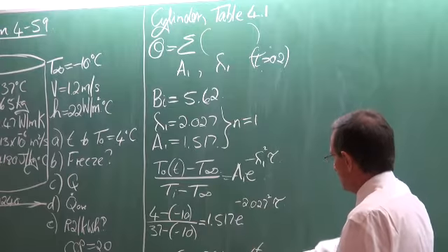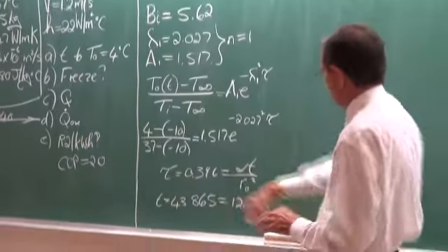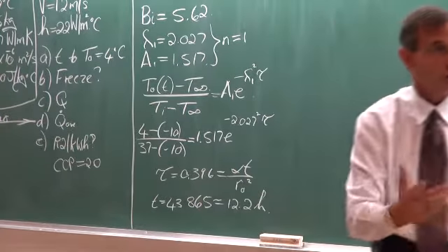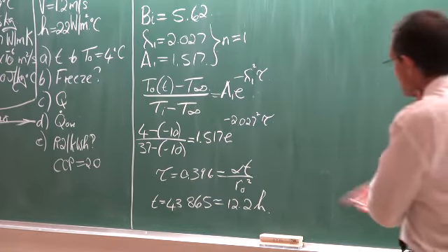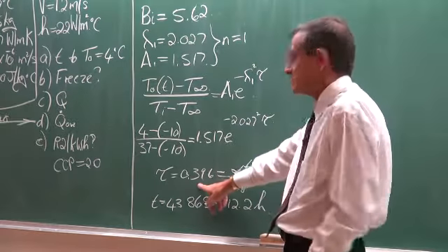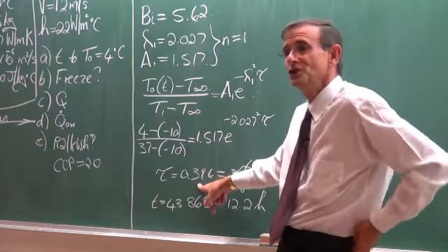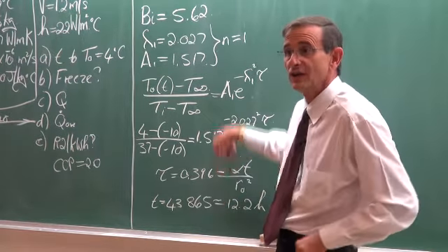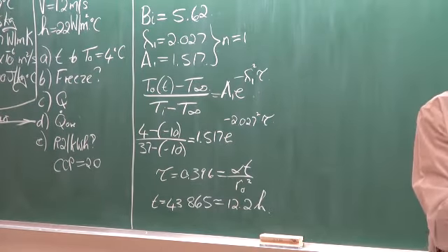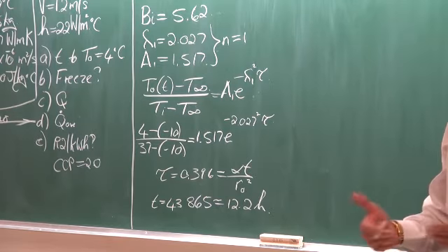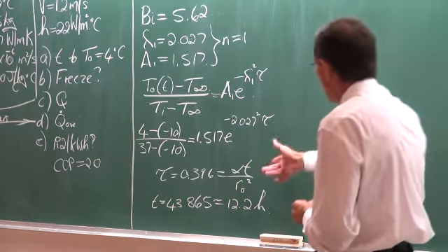We've calculated the tau, which is about 0.4, so it looks fine, and it says that we can use this approximation. If tau was far less than 0.2, then you would have to calculate also the other roots and the A values for n equal 2, 3, etc., to get the result to be more accurate.